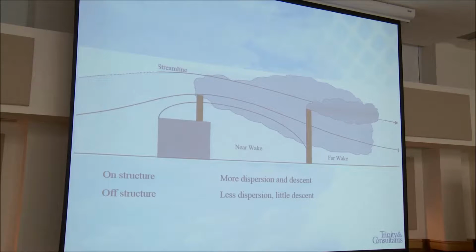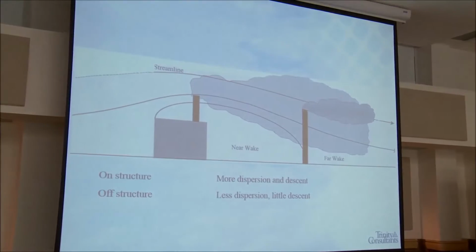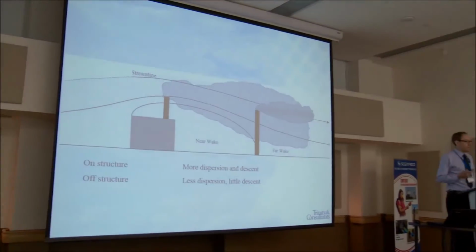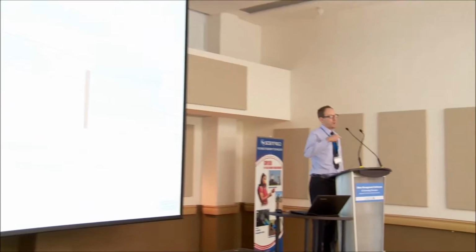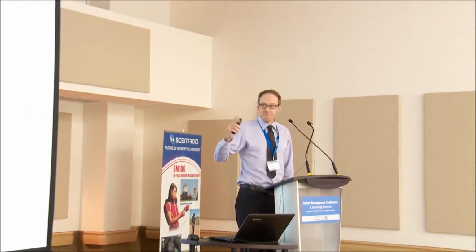The physics and geometry of buildings are quite complex. They affect plumes in a variety of different ways. We need to know this when recommending a model, and that's fundamental to what we're going to be talking about today. Because if we're looking at fence line concentrations, or if we're looking at how receptors are impacted, it's not necessarily just ground level that's important. It's not necessarily the fact that there's a tall stack that's important. It really depends. If I was to build a condominium right next to that tall stack, we could have very high odor impacts at the top floor and nothing at the bottom floors.